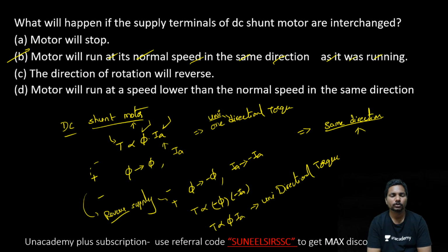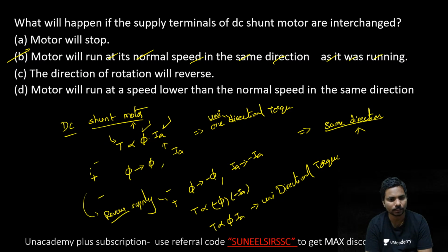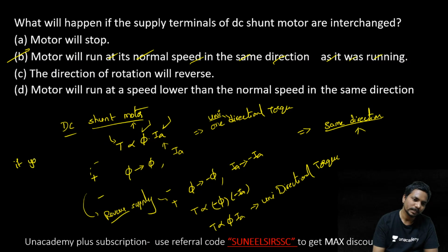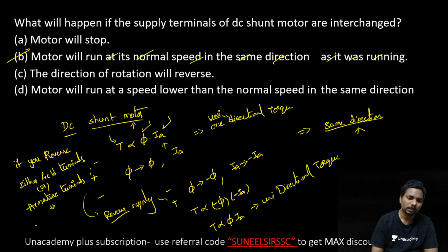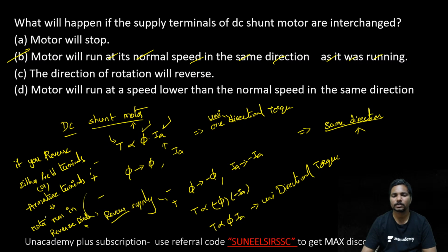So if you reverse either the field terminals or the armature terminals, the motor runs in the reverse direction. But not both, students, either field or armature only.